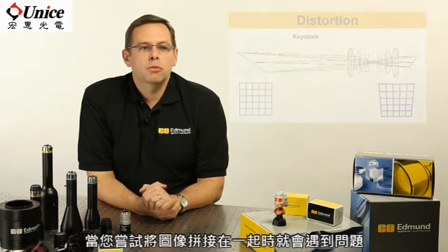This can really run into problems when you're trying to stitch images together. If you have any sort of keystoning effect, and there can be some amount in almost any imaging system because it's nearly impossible to get everything perfectly perpendicular between the sensor, the optical axis and the object itself, and you try to stitch these images together without taking keystoning into consideration, you can get a kind of warped image as you do each one of the stitchings. It also will lead to measurement inaccuracy at the tops and bottom of the image potentially because you have different fields of view and your calibrations could be off.